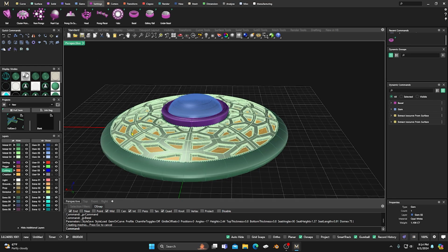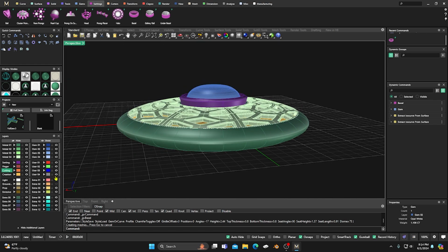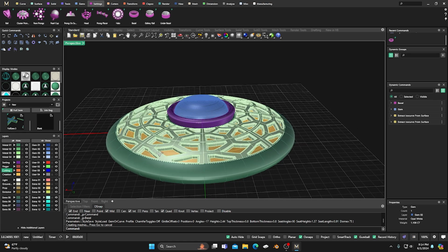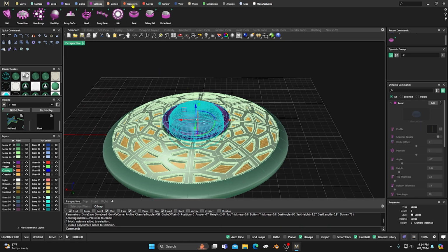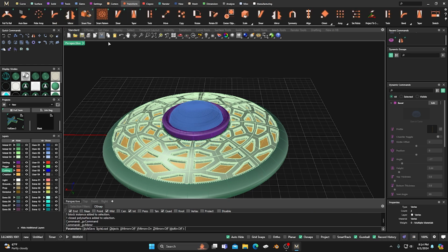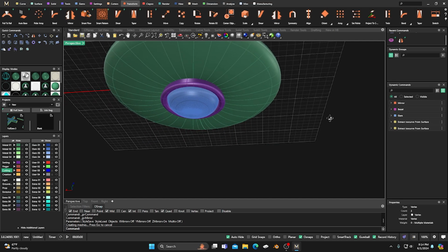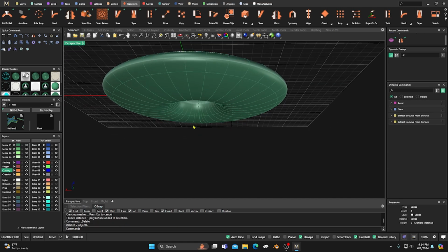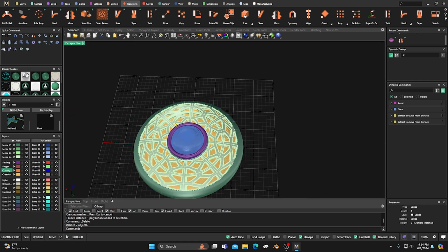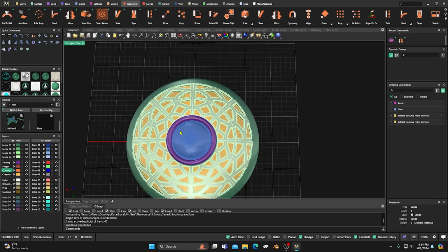Just go ahead and do the same process that we did here for the Smart Flow on this side. You can flip those curves, those gray curves, over to the other side and do the cutout and do another pattern on that side. Just select your stone and your bezel, go to transform, mirror in the Z direction, and accept that, and you have the one on the other side where you can do a whole other pattern, right? So let's just get rid of that for right now. We don't really need it, but it's an option that you have. You could do a double-sided so the customer could have a little bit more options.